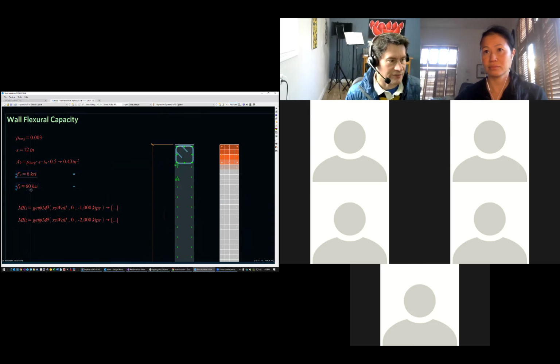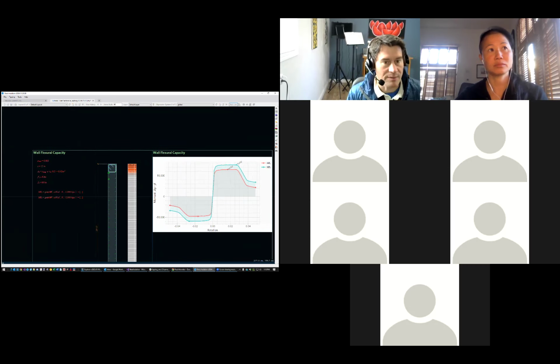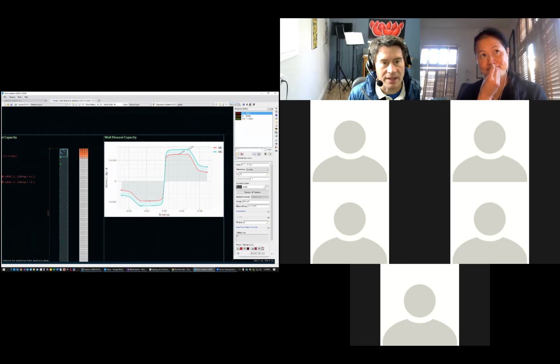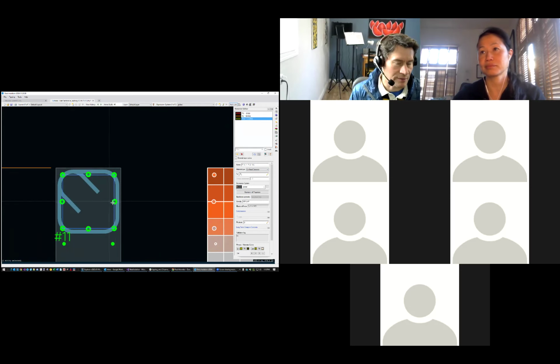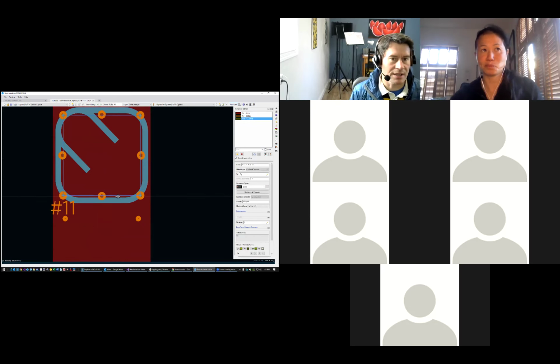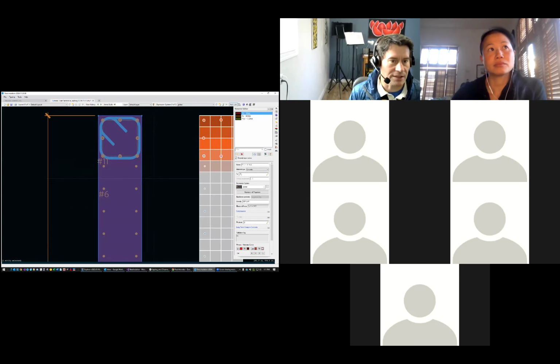We created an expression for the strength of concrete and rebar, and then we used the fiber material sidebar to create these fiber materials, and there's our concrete material referencing our concrete strength expression, and the rebar material referring to the rebar strength expression, and then we also had a confined concrete bit here that we drew up later in the analysis, and I can always double check what's what by checking the box to override layers, and I can see here's my confined concrete material, my rebar material, and my unconfined concrete material.